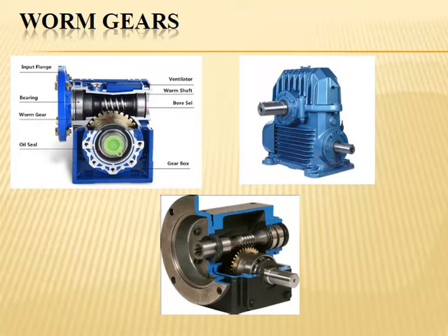The lubricants widely used in worm gears are straight mineral oils and gear oils. In the gear oils, various SAE grade gear oils are used. For example, SAE 75W, SAE 80W, SAE 90, SAE 140 and SAE 250 are widely used.